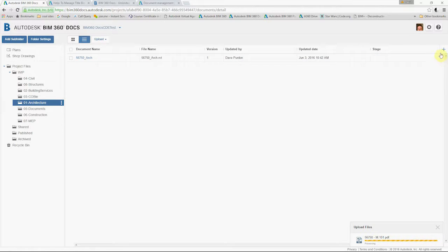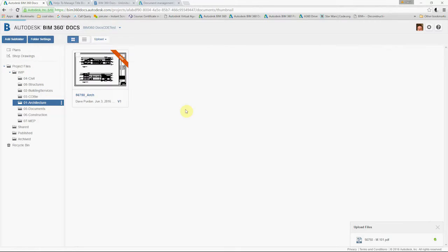So what you can do is you can add metadata to files from within docs that you may not have stored on the actual files themselves. So you see, I'm just looking for this little drop down. There we go. So now I can change the stage of that document or that model. So I can say it's revision 0, revision 1, revision 2. Again, depending on my permission level, I have control permissions. I have the ability to add attributes to folders as well as files themselves.